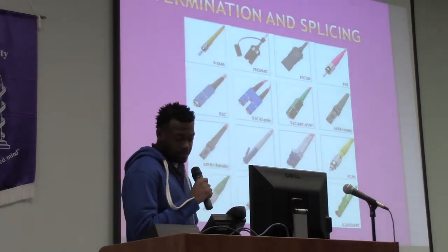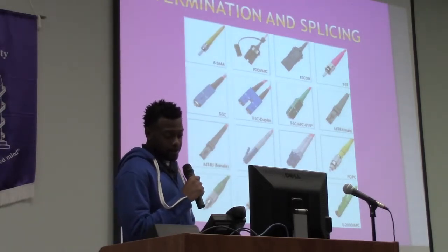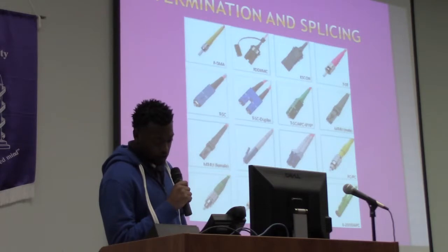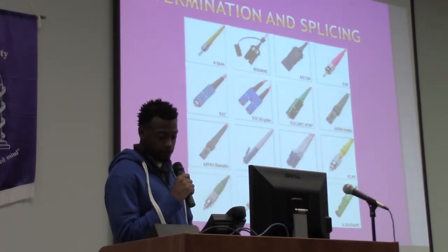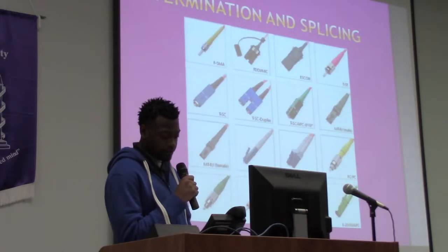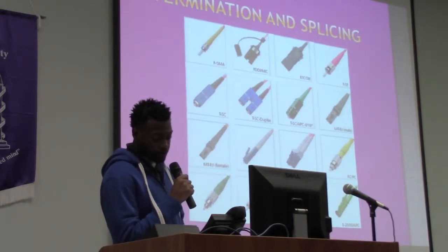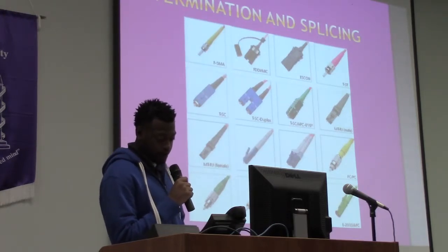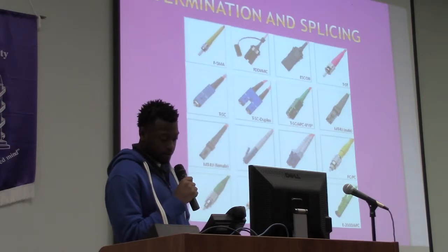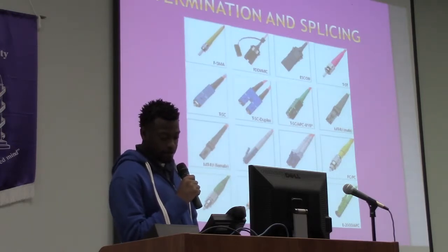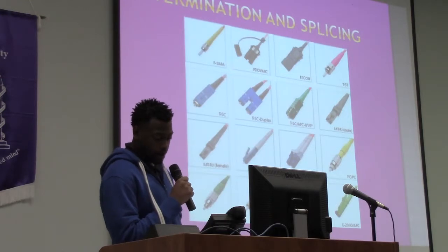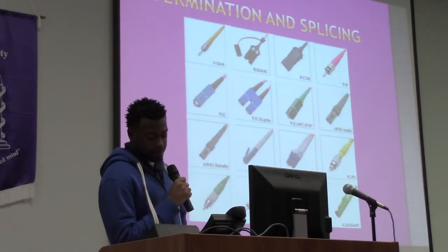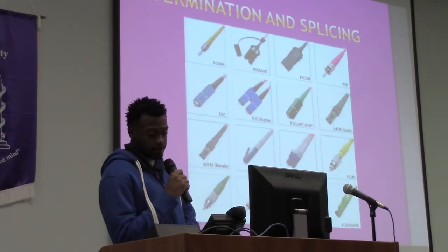So that is pretty much an example of the process of making optical fiber. The standard optical fibers are made by first constructing a large-diameter preform with a carefully controlled refractive index profile, and then pulling the preform to form the long, thin optical fiber. The preform is commonly made by three chemical vapor deposition methods: inside vapor, outside vapor, and vapor axial deposition. And then the optical fibers are connected to terminal equipment by optical fiber connectors.